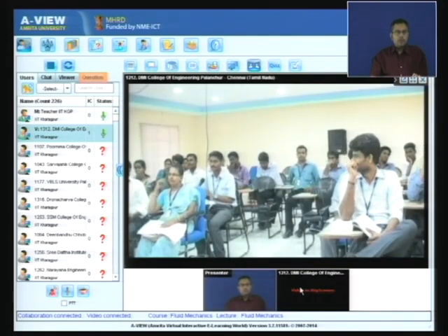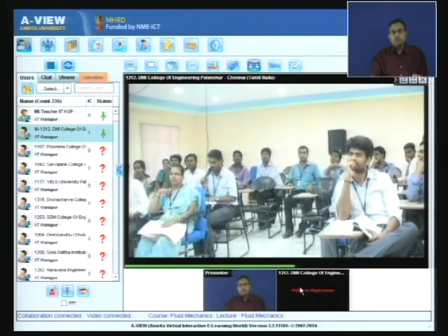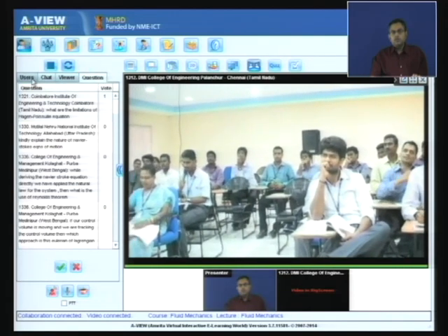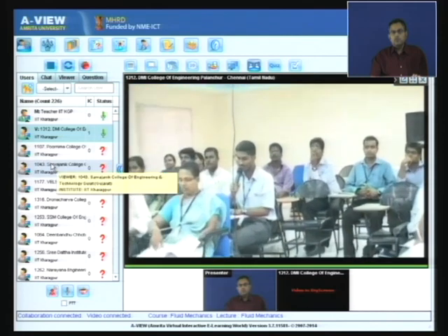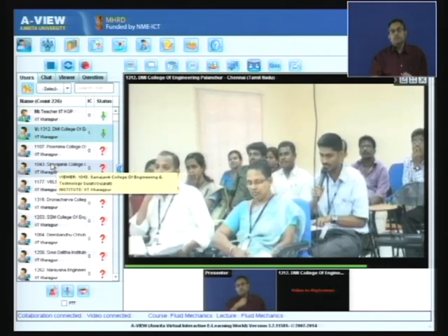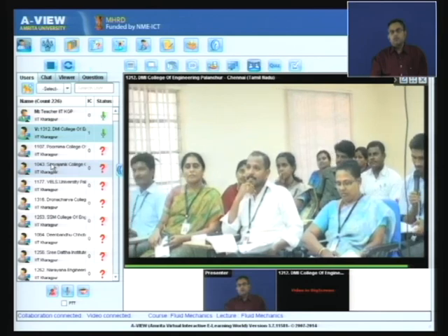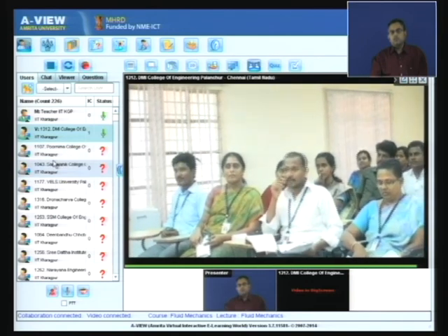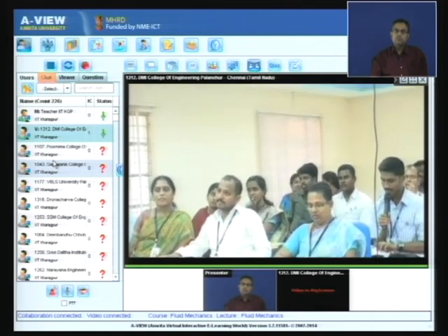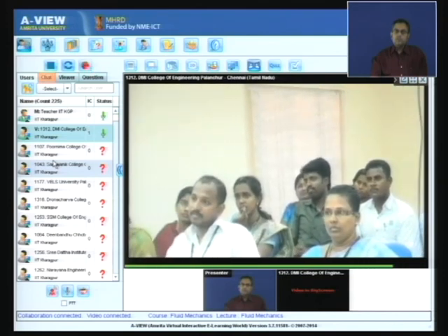1312. Sir, good afternoon, sir. Good afternoon. Sir, I have one clarification on that second tutorial problem. In that problem, the equation u is equal to 1 by mu dp by dx into y square plus c1y plus c2. Yes. The first boundary condition, apply that y is equal to 0, then u is equal to 0. Yes. Then the c2 value will be 0. But the second boundary condition, sir told us u is equal to 1 by 2 mu into dp by dx capital H square plus c1h. Sir, how does that 1 by 2 mu come, sir?